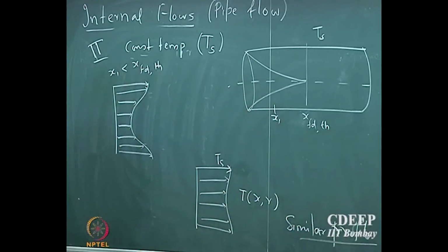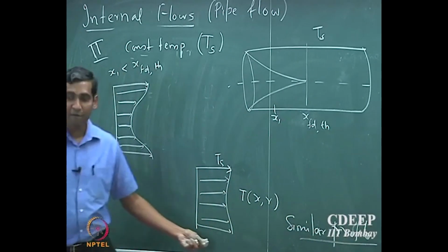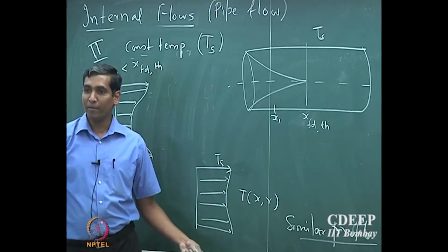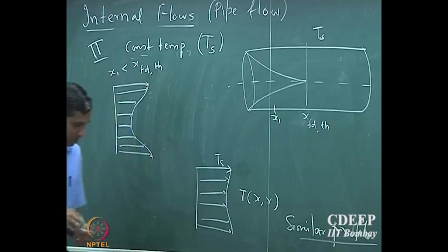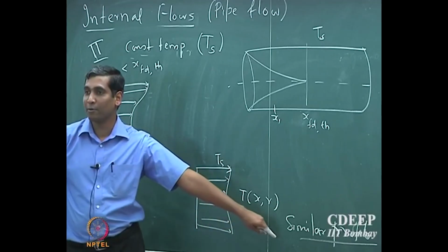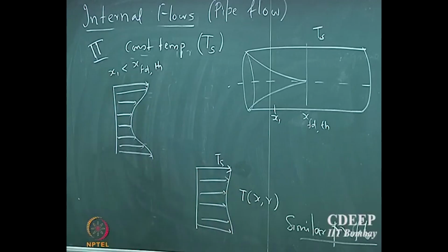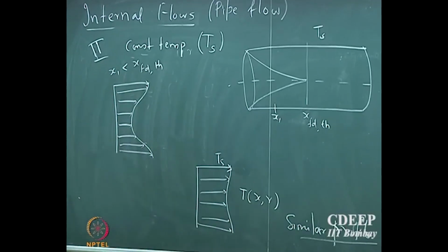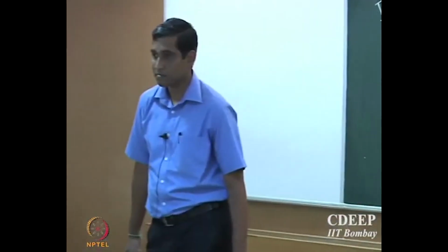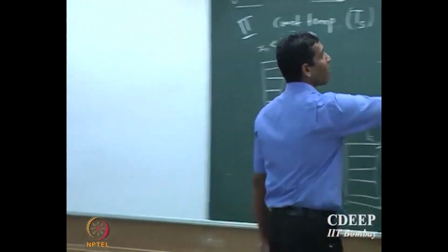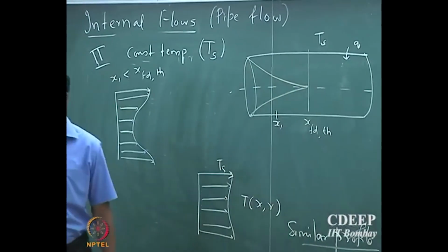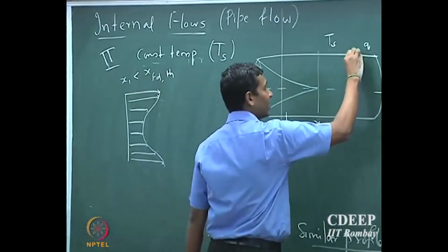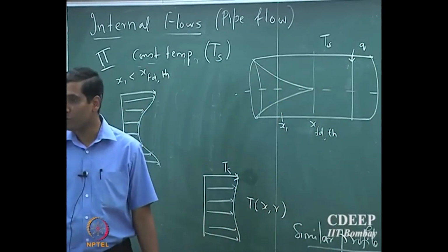and we are actually going to capitalize on this aspect that the profile is similar, and we are going to attempt to solve the problem and get the heat transport and mass transport coefficient, okay. So before that, before we even understand what is a similar profile, we need to have a reference, right? Because even if you have constant temperature, you have a flux of heat transport, right? So until the fluid temperature equilibrates, right, because of Newton's law of cooling.